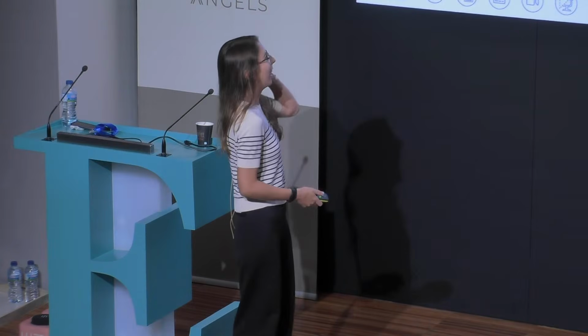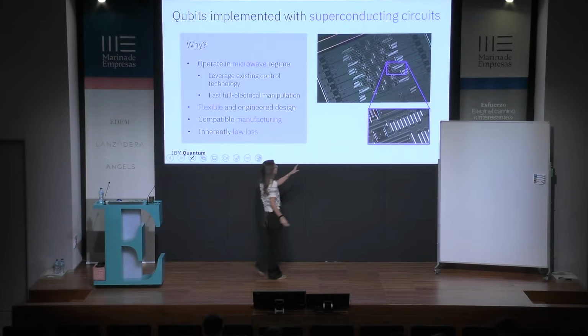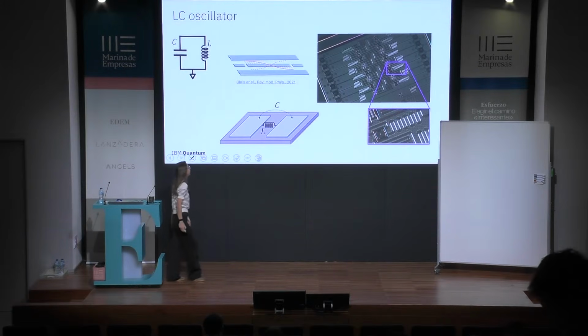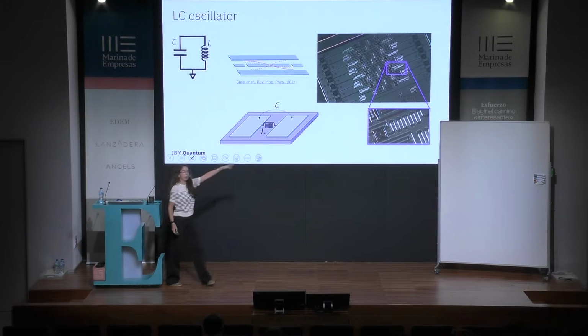So with this, we turn now to a bit more of a technical part, taking a bit more in detail at how these elements that we see here in the image look like. I just anticipate this is a transmon qubit that's coupled to a meandering superconducting resonator, but let's describe them a bit more mathematically now. We first start with the meandering part, which is the LC resonator. These type of resonant objects can be implemented in many different ways. Whatever resonates can often be well described as an LC oscillator to some level.